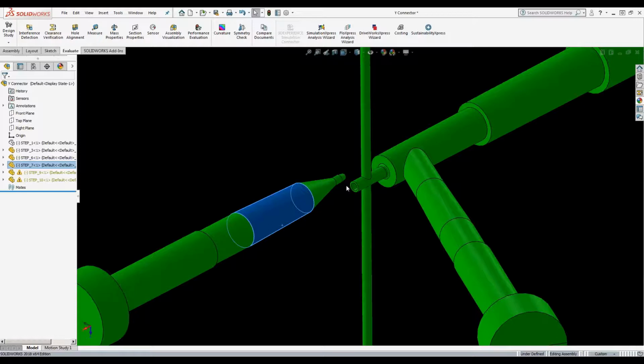No, I mean, really the key is to make sure all the pins don't move during injection. The pressure will sometimes make the pins flex. These locking features assure that we get consistent wall stock and a concentric, uniform diameter on inside and outside of the part. And really the challenge is keeping everything straight, centered, with good clean shutoffs,